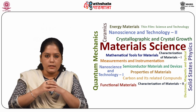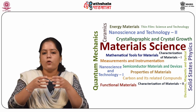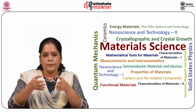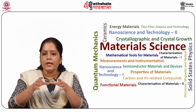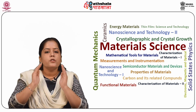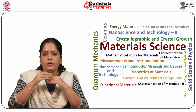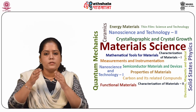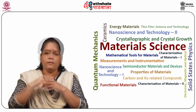So if a crystal is subjected to a general state of stress, that is sigma ij, then each of the strain components epsilon ij is related to each of the stress components by this relation: epsilon ij equal to Cijkl sigma kl.